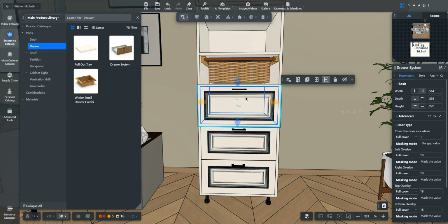But you should notice that if you make it as an onset, this drawer fascia will be extended 18 mm on all the four sides. But in this specific requirement, I want this drawer fascia to get extended 18 mm on the left, top and on the right, not on the bottom, because on the bottom there is also another drawer. It might eventually create an overlap here, right?